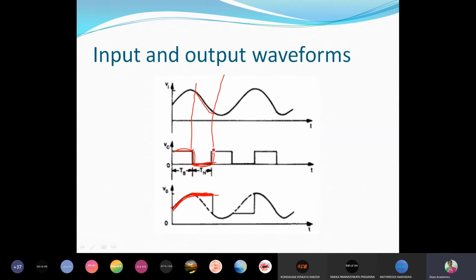When the control voltage goes high again, when it is 5 volts, then whatever input voltage is applied, the capacitor goes to that voltage. If it is low, it will go to that; otherwise, if it is high, it will go to that. And now, as long as this control voltage is there, the capacitor is charged to the input voltage. So this is the input voltage. Therefore, during this time, the voltage across the capacitor is this much.